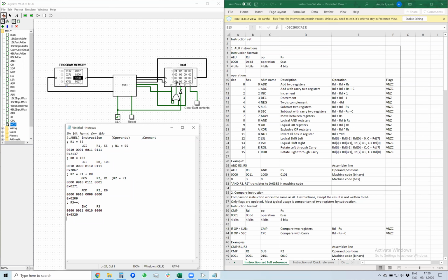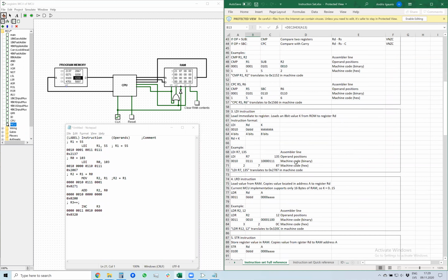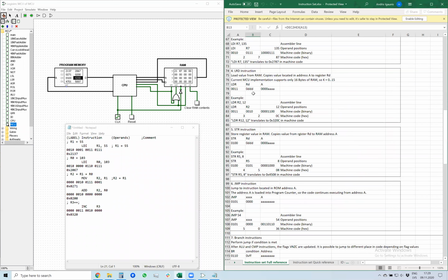They will all be written in random access memory. So for this reason, we have instructions called load from RAM, which are called LDR, as in this case, or sometimes simply LD, like load, and store to RAM. Copy register value into RAM is either ST or STS or STR. They have different names.